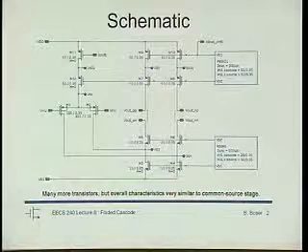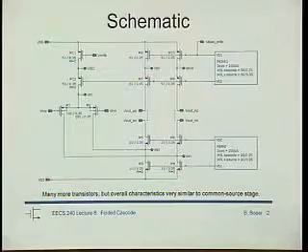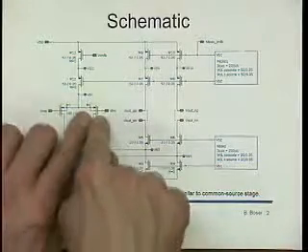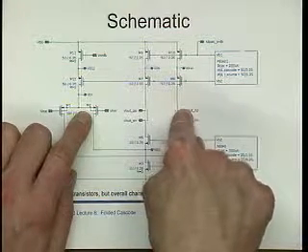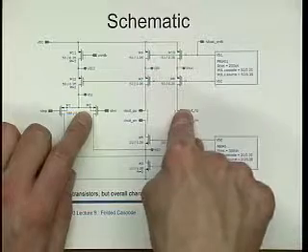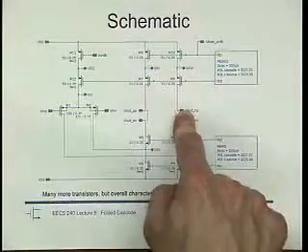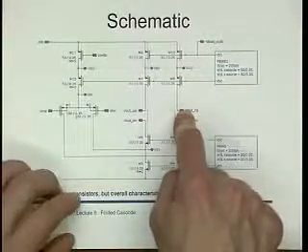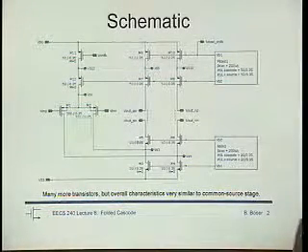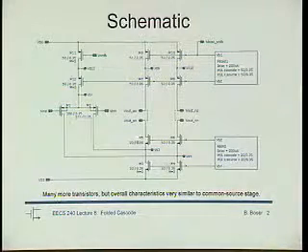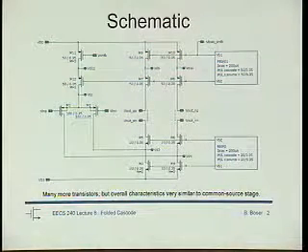And that's basically the same thing as we have in the common source stage. The common source stage has basically the transconductor, gm, that drives into the output that gives us a unity gain bandwidth of gm over CL. Or then a pole frequency that is the unity gain bandwidth divided by the open loop gain, right? Whatever that is. So rather than specifying what the dominant pole is, I usually prefer to specify what the unity gain bandwidth is, because otherwise I get this number out into the picture that is not so interesting.